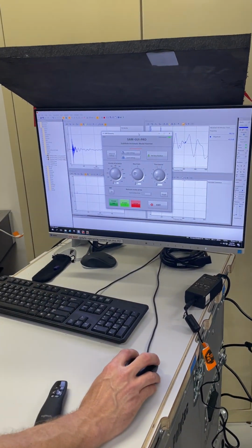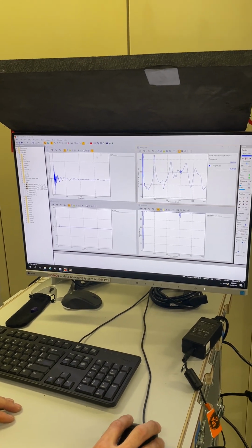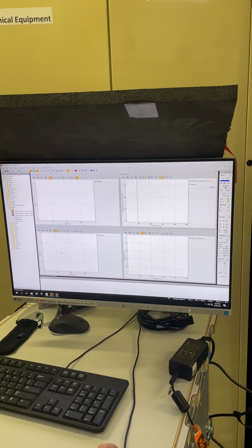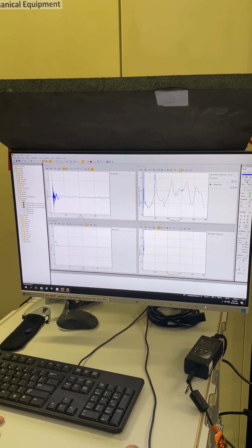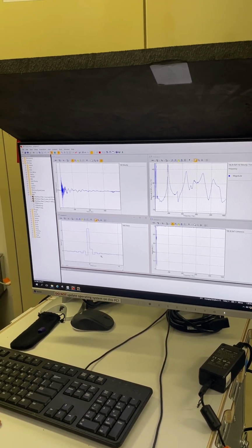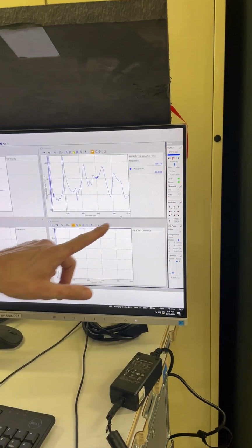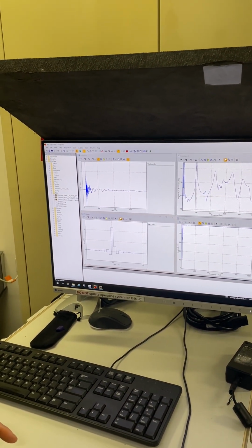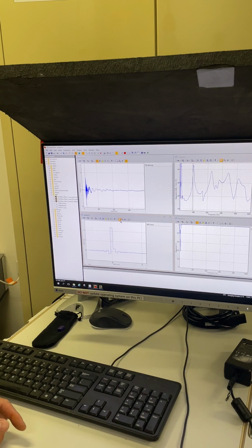If we come back to the software side here, I'll have a look at the PSV software. I can just stop this one or restart it, and when I restart it here, we'll see these are my impacts. It's a relatively low level force impact, but if I zoom in, we can see the impulsive excitation. Relatively coarse temporal resolution at this moment. I've only got an acquisition bandwidth up to approximately 1 kilohertz. And here's the response being measured by the laser Doppler vibrometer on one of the measurement points. And you can see the contribution of a series of different resonant frequencies at the various different resonances.